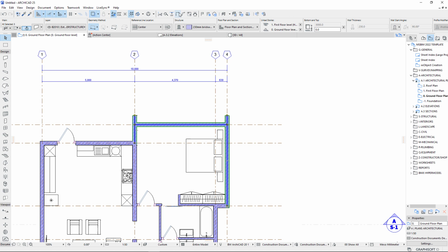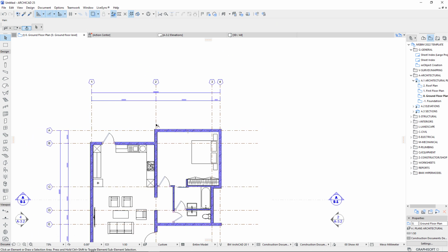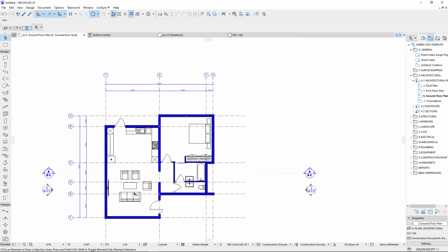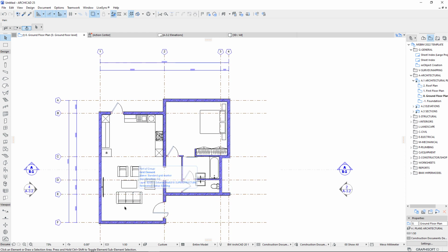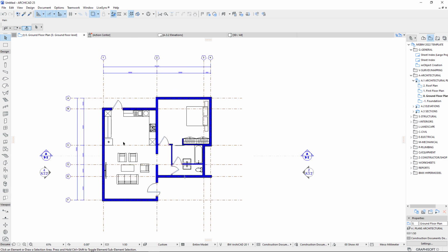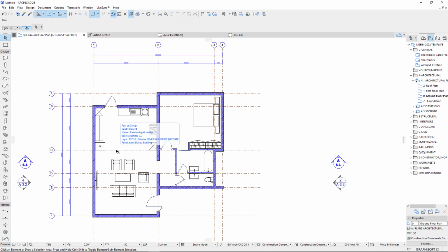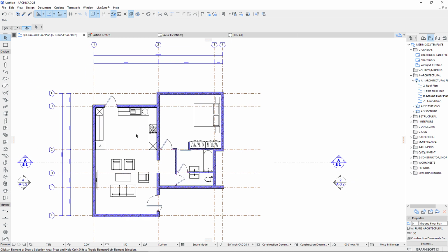And then select these ones and fillet or intersect the corners. So yeah, perfect. What I want here is to check the distance between this, which is 3.5, and that's 5 meters, 3.5 in a lane. Perfect. I was saying the next step is to place the floors or the slab for this.